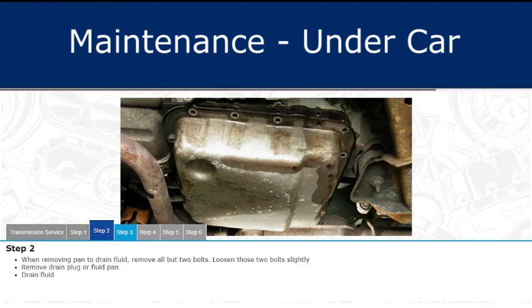When removing the pan to drain fluid, remove all but 2 bolts. Loosen those 2 bolts slightly. If equipped, remove the drain plug to drain the fluid. Otherwise, carefully remove the fluid pan.